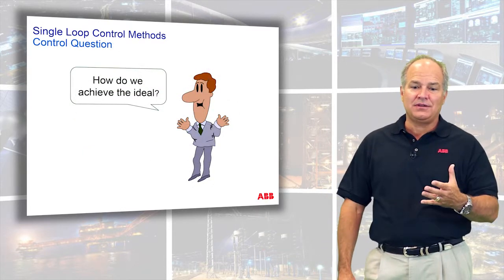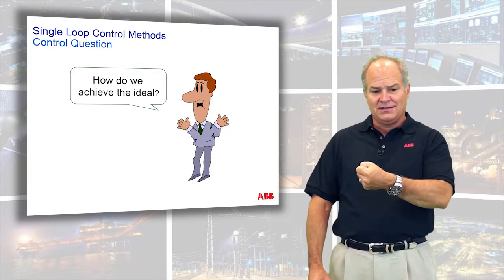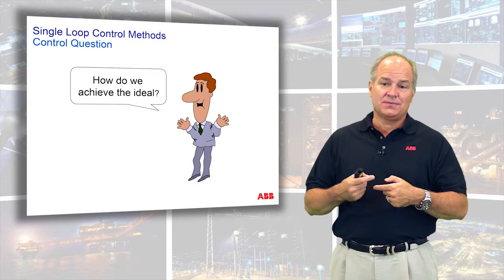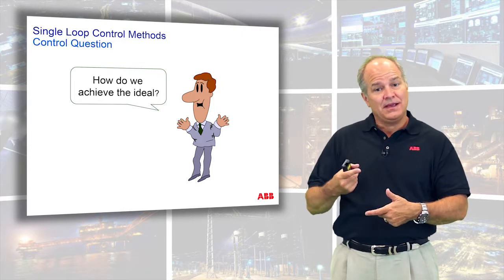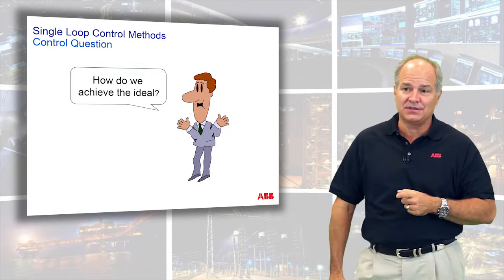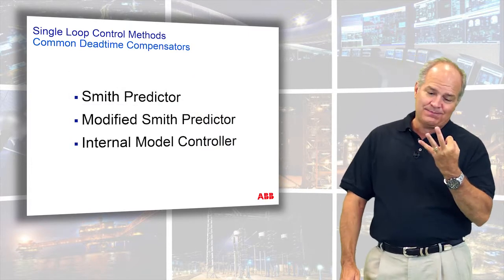How do we measure the process without dead time? Well, you can't physically measure the process, but we can simulate it. And if we simulate it, then we can pull from the undelayed process. And that's what we're going to talk about. There's 3 primary